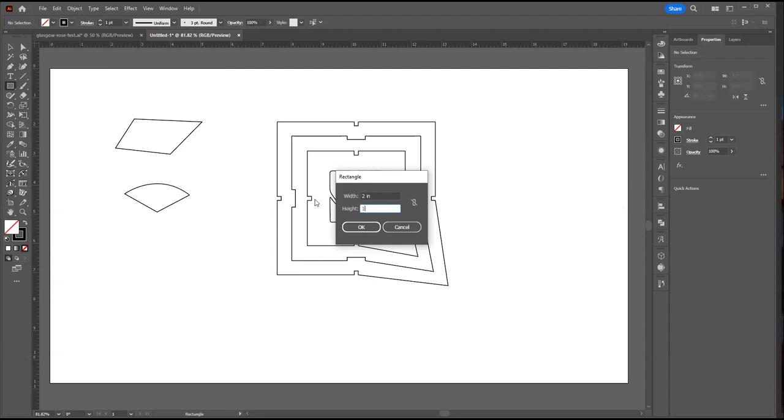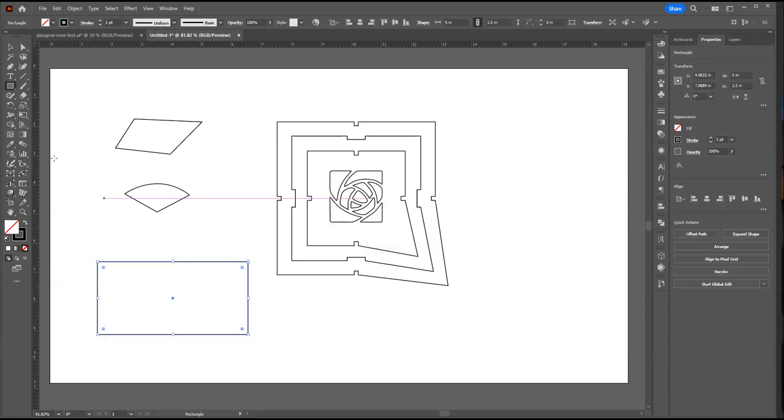Now, I feel like there's a lot of running around here because each tool has got stuff that you can do with it. In this case, you can constrain. So for example, if you say 2 and 1 is my base size, but if I make something bigger, I want it to stay in that ratio. So now if you come in and say, I want to make a 5-inch box, then it does the math for you and it creates the 2.5-inch height based on your constraints. So we're going to make a box.